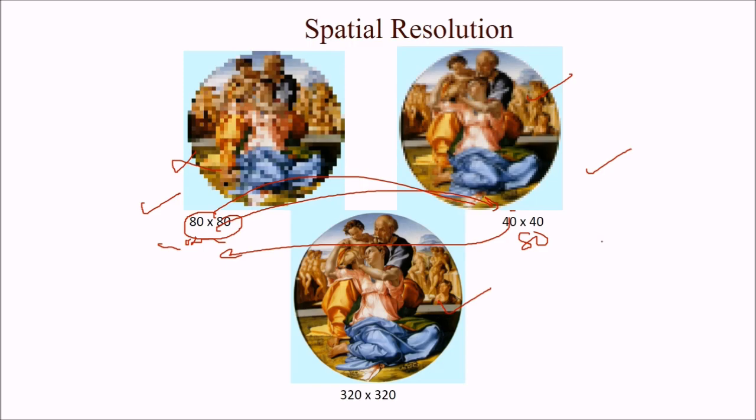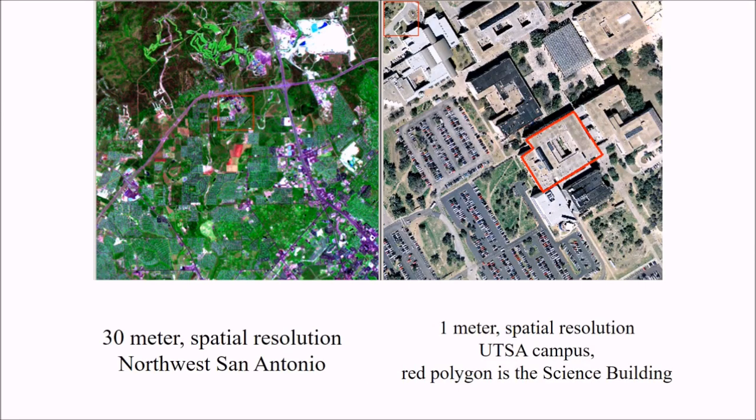But what is the spatial resolution? Spatial resolution is actually this area. If this area is being seen at 1 meter, this area is being seen at 30 meter. The resolution says that you can very well identify the object. So spatial resolution is the capability of the sensor to discern 2 objects on the ground. That is the minimum level, or so you can say a pixel in an image. In layman language, the pixel size is your spatial resolution.